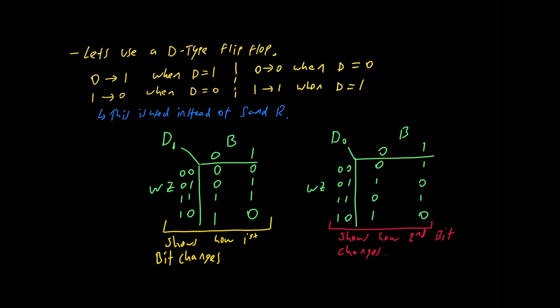This can be a complex process to follow, so make sure to stop the video and compare the table to the Karnaugh maps. Once all is complete, you can loop ones in the Karnaugh maps to find the logic required. The diagrams follow from here. This behavior will represent a score counter that counts upwards from 0 to 3, then back to 0 if it gets higher than 3. To display this on a screen, you would need logic from the outputs of the flip-flops to achieve this.